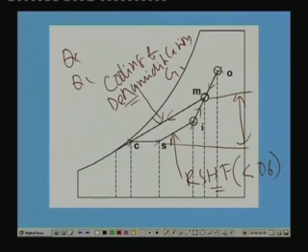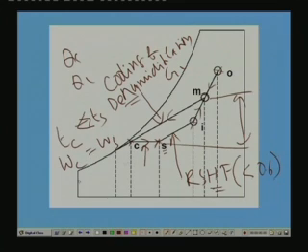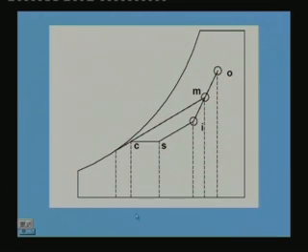For that purpose, at this point air flows through the reheat coil, and in the reheat coil it is sensibly heated. In the reheat coil the temperature increases from Tc to Ts, so that the point S lies on the room sensible heat factor line, so that it can take care of the latent and sensible heat loads. Since it is a sensible process, Tc will be lower than Ts, and Wc will be equal to Ws, so no change in the humidity ratio.